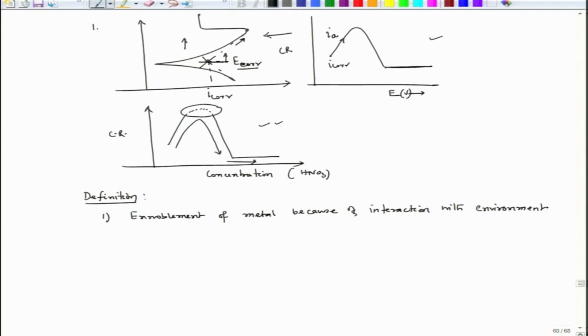But if you see this graph, the corrosion rate is decreasing, and this decrease in corrosion rate is because of an increase in potential. So, that means potential has gone up. We have seen that if we have two metals joined together, the metal which is the cathode has a higher potential than the metal which is the anode. And here remember, the cathode does not mean only the reaction related to the metallic part of that particular cathode.